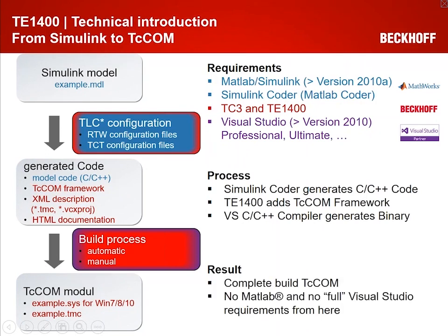The result is a complete built TcCOM, which consists basically of a .sys driver and a TMC file, which is a TwinCAT Module Class description file. And from these binaries, we don't need any more MATLAB or full Visual Studio. From here we can use TwinCAT only, if we like.